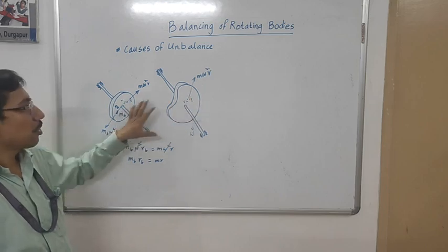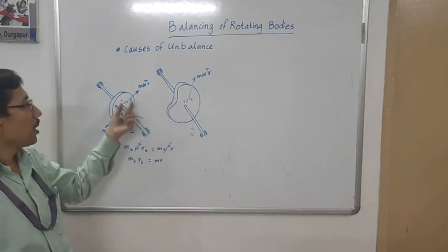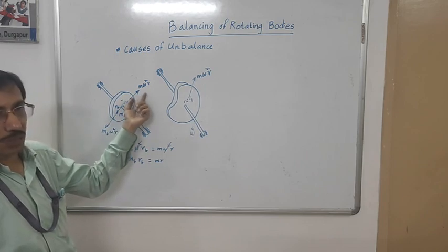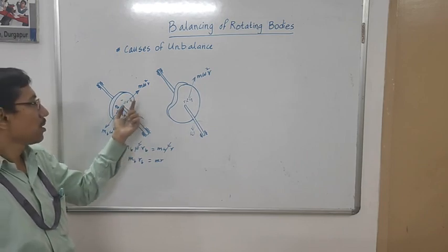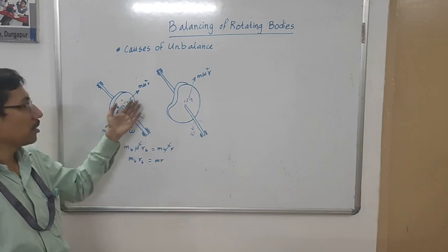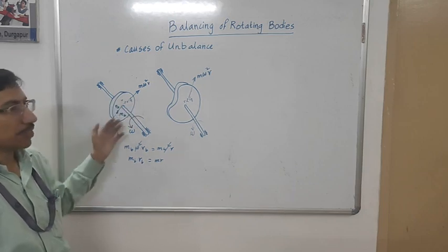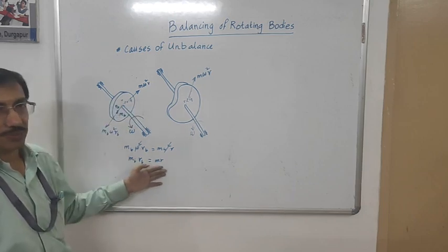The same principle can also be adopted here. So whether it is symmetrical or unsymmetrical, it doesn't matter. If we have one unbalanced force in the plane of rotation, we can put one balancing mass at the diametrically opposite location and balance it. So this is our expression.